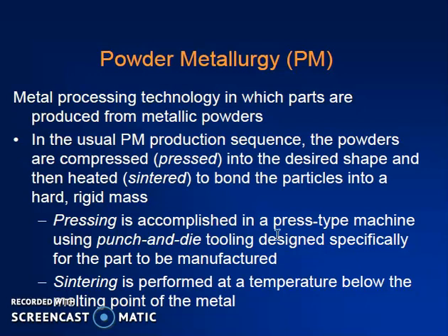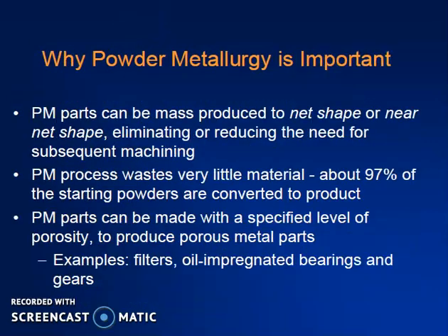So, pressing is accomplished by a press type machine using punch and die tooling designed specifically for the parts to be manufactured, and sintering is performed at a temperature below the melting temperature of that metal. So, this part is important while processing the metal powders. Then why is powder metallurgy important for any engineer?